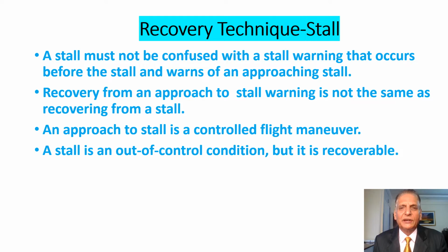Now we shall discuss recovery technique from a stall. A stall must not be confused with a stall warning that occurs before the stall and warns of an approaching stall. Recovery from an approach to stall warning is not the same as recovering from a stall. An approach to stall is a controlled flight maneuver, but a stall is an out of control condition, but it is recoverable.